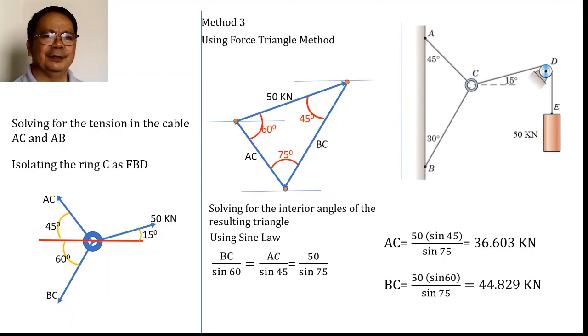So guys, that is what I mean by what else you should know when dealing with a force system in equilibrium. You learn how to simplify the solution using the method of selecting a rotated axis, or the application of the force triangle in solving the problem. As well as the concept that when you have 3 forces in equilibrium, then the 3 forces must be concurrent.